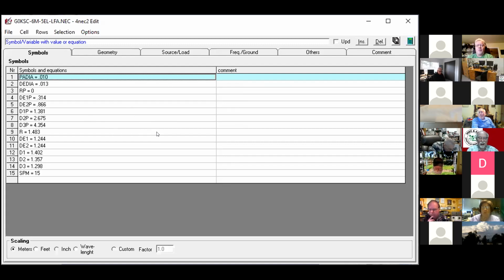This is a highly optimized antenna. What aluminum is it using? It's probably 6061 T6 at 13 millimeters, or a half an inch. A half-inch hollow? Half-inch hollow. Now, the reason you use a half an inch is for that folded dipole. You need to insert the end items in there. So that's 3/8 inch tubing. And you bend them and stick them in. And that makes your whole folded dipole for your driven element.